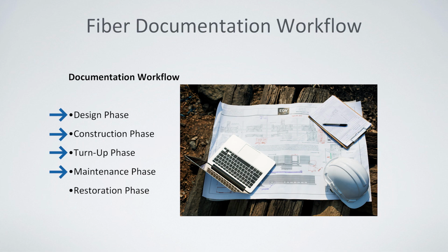During the maintenance phase, every new splice, cutover, or node split must be recorded to ensure documentation remains current. Finally, during restoration, technicians rely on these records to quickly identify priority fibers, reference splice locations, and restore services efficiently.